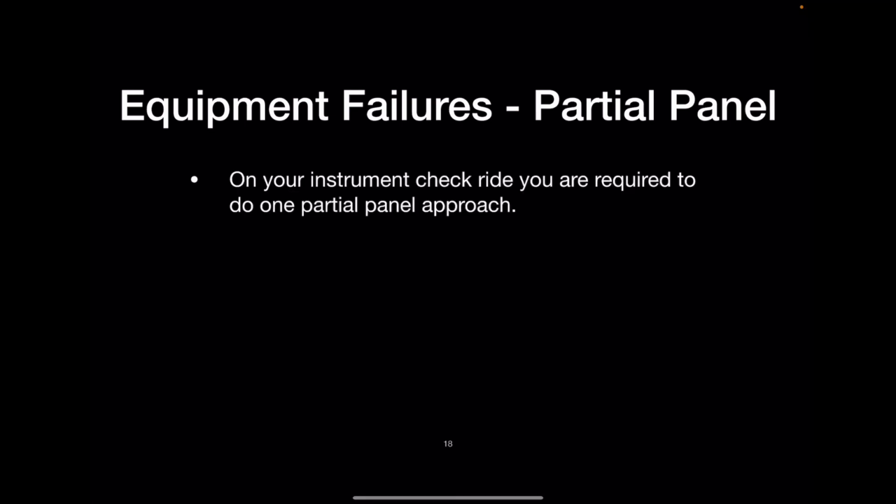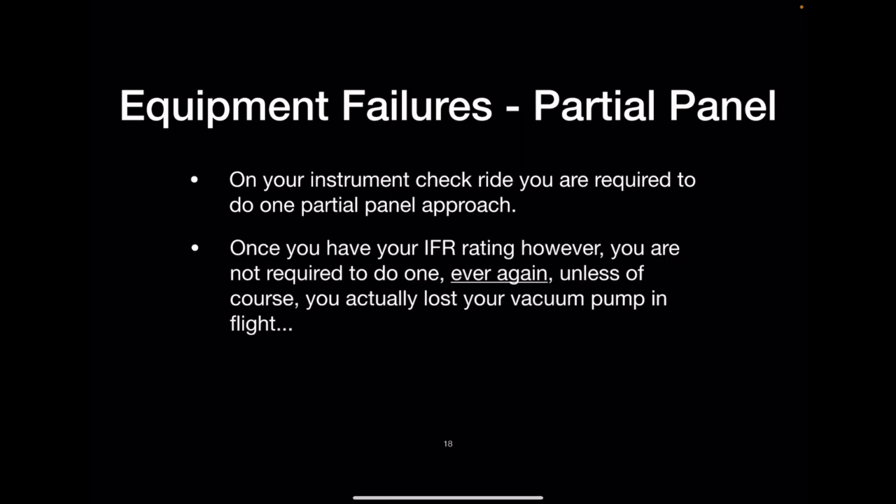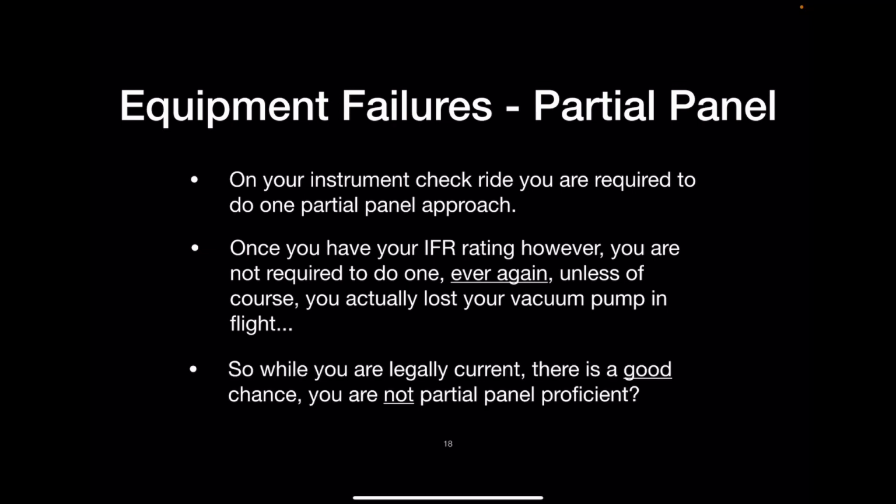Now, on your instrument check ride, you're required to do one partial panel approach. Once you have your IFR rating, however, you're not required to do one ever again, unless, of course, you actually lost your vacuum pump in flight. So while you're legally current, there's a good chance you were not partial panel proficient.